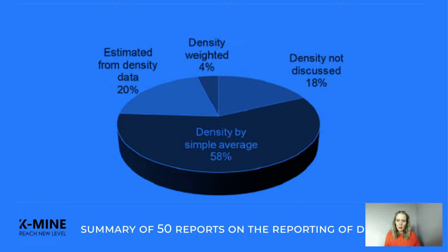In the past, the term specific gravity was commonly used to refer to the dry bulk density of rocks, but this term is now considered inaccurate and not recommended. Instead, the more appropriate term is dry bulk density, and it represents the dry mass of a rock excluding any natural moisture per unit of actual in situ rock volume while accounting for porosity. It's a more precise and meaningful way to describe rock densities.